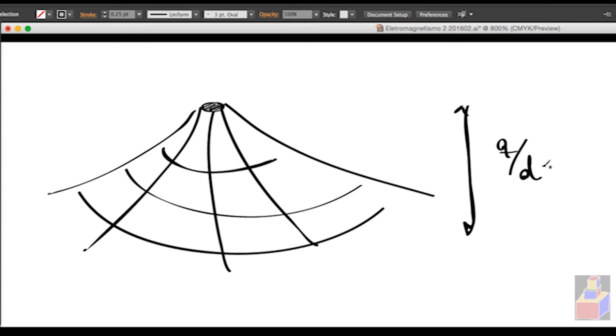Yes. Previously, you said that to avoid the singularity, we define d. If it's less than d, then it's going to cut at that maximum value. So how big a value will we use for d? You choose it. You play with it in MathCAD. You choose a value. For instance, suppose that your domain is 2 by 2 units. You can choose something much smaller than that. Let's say 0.1, 0.05. It's okay.